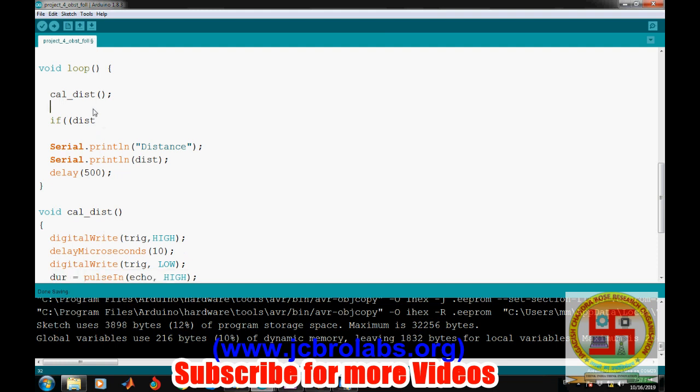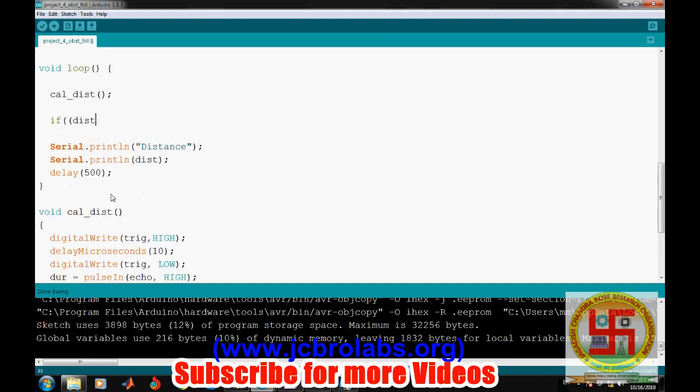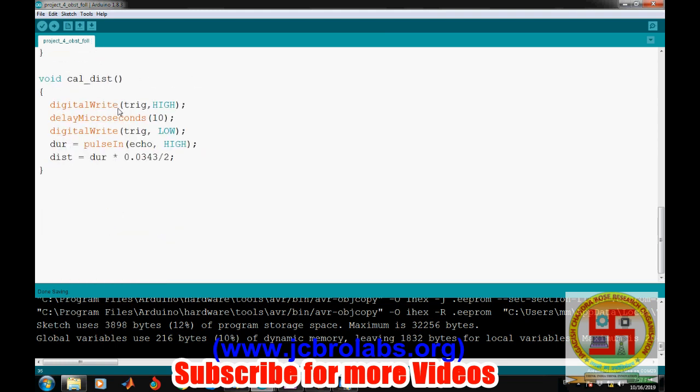Okay, we'll write our logic here. So distance has been calculated from this function because we have called it here. So if distance is greater than 9 and distance is less than 15 centimeter, right, it should stop. Okay, so we'll write a function to stop the motor. So what should be there?